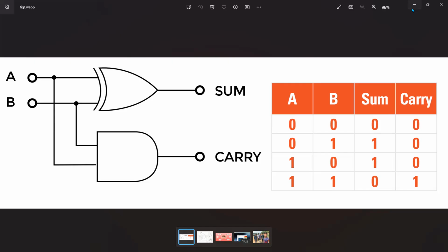Now we have to understand some basic knowledge about Verilog. In Verilog, there are some signs which represent the OR operation, AND operation, XOR operation, XNOR operation. So here, S is equal to, if you remember, in here, sum is equal to A XOR B. So we have to write sum is equal to A XOR B and carry. That means C. C is equal to A and B, right? So S means sum.